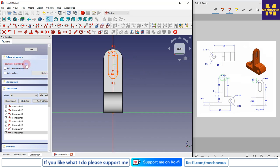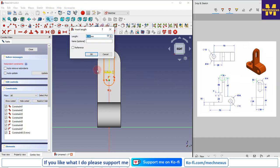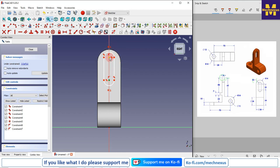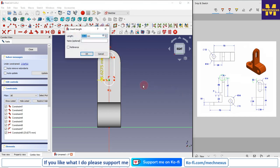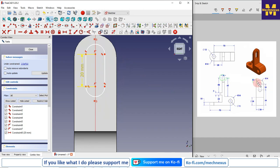So here is a conflict, I will delete it, and now the center to center distance is 20, so I will give here 20. So this is the horizontal dimension, so I will select this and this, and I will give a horizontal dimension of 20, and the slot radius is R6, so I will select this and I will give the radius 6,